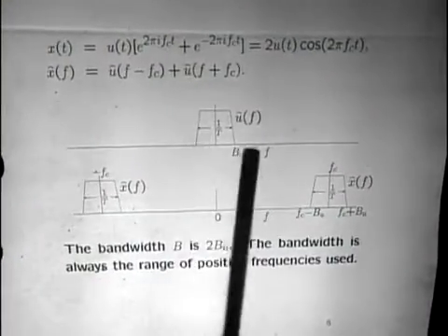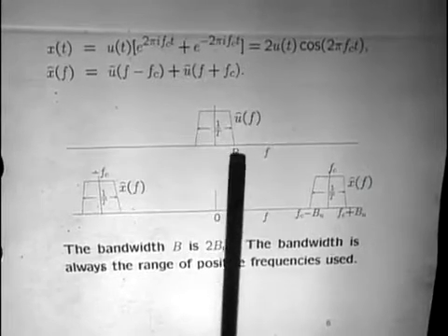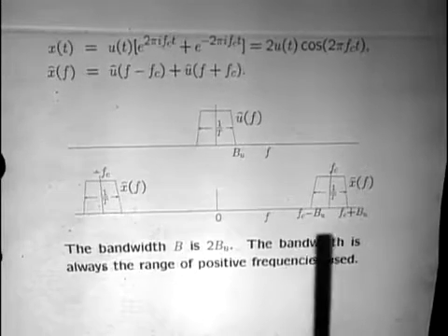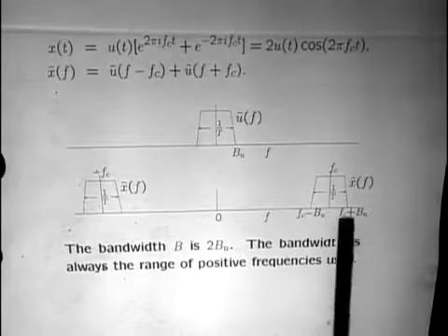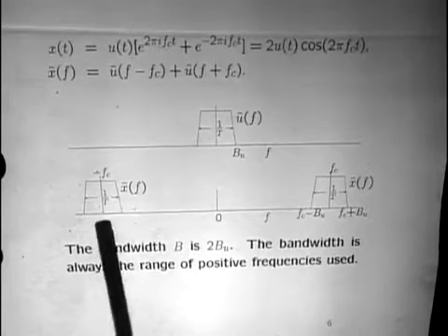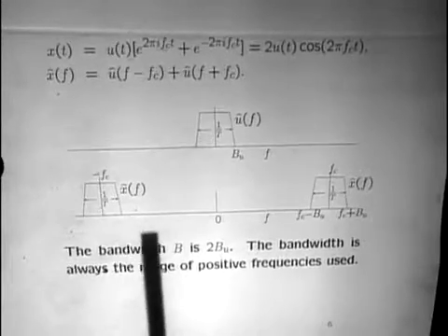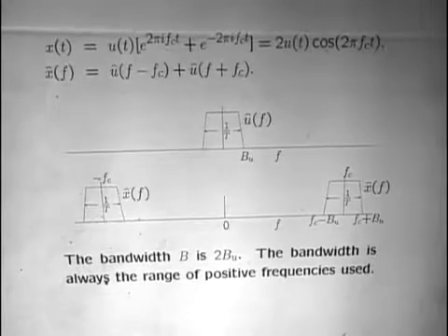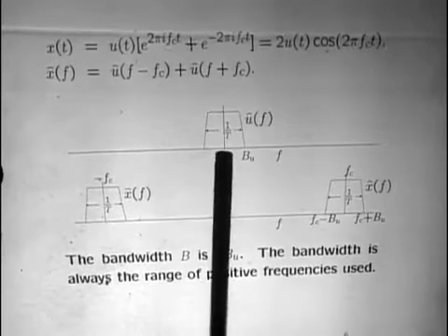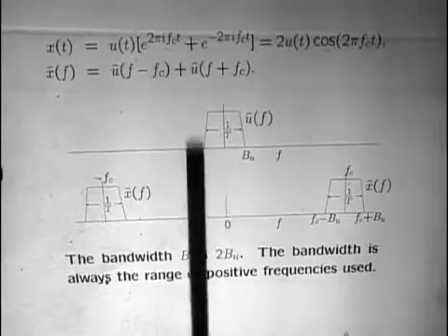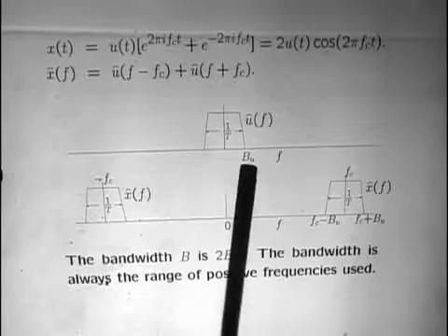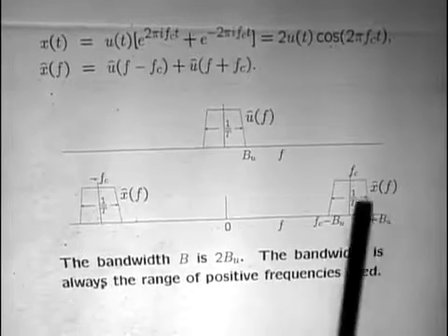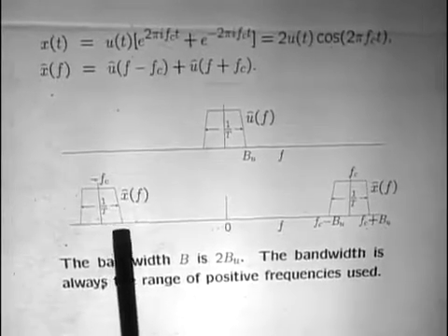But anyway, when this thing, which exists from −B_u up to +B_u, gets translated up in frequency, we have something which exists from fc − B_u to fc + B_u. And this negative band is down here. Now, we're going to assume everywhere, usually without talking about it, that when we modulate this up in frequency, the bandwidth here, this B_u, is less than the carrier frequency. In other words, when we translate it up in frequency, this and this do not intersect with each other.